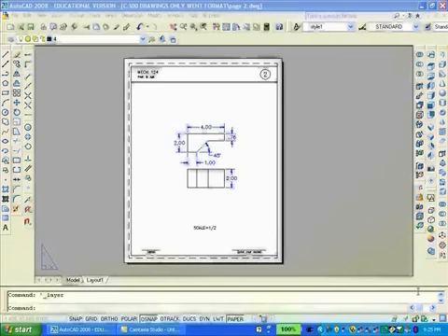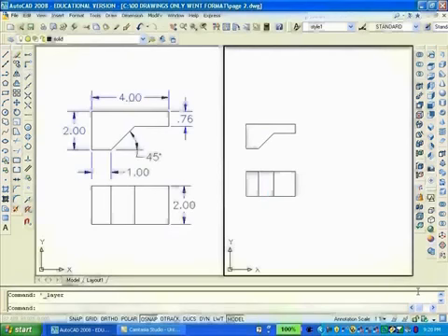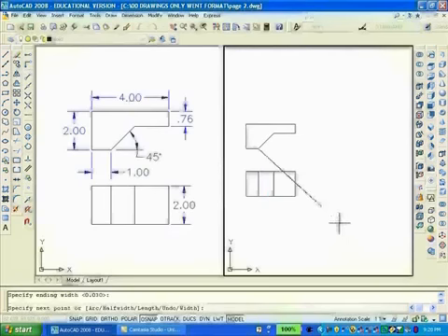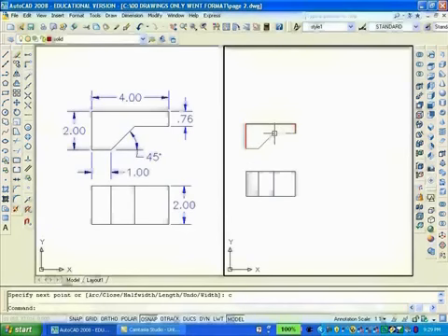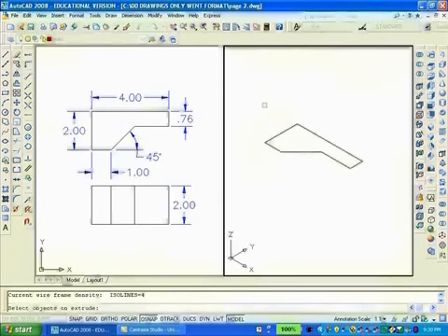Tutorial 2 is another simple detailed drawing. A solid model of this object will be created and placed in the upper right corner of the drawing. I'll use a polyline and trace over the perimeter of the top view. When that is completed, I'll move the tracing to the right and go into the southeast isometric view. Now the object will be extruded to a height of 2 units.